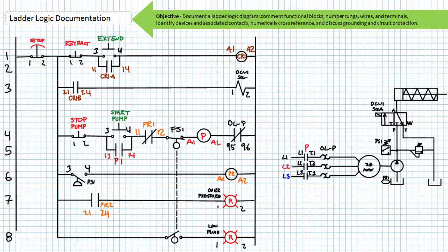Finally, recall that switches being held in their activated state can be identified using one of two conventions, the gravity convention and the arrow convention. I prefer the arrow convention since it is immediately recognizable. The observant among you will have noticed that the mechanically interlocked float switch is not in its deactivated state, but rather being activated using the gravity convention. Ordinarily, gravity would be pulling the top switch open and the bottom switch closed. This may have escaped your notice, and for this reason, I highly recommend the arrow modifier.